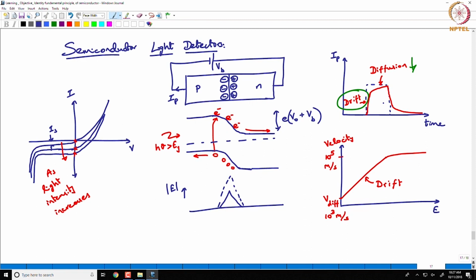So, those will contribute to the initial photocurrent, and then you have the slower charges coming out of this photodiode, right. The ones going through diffusion would have a slower time constant, they will come later essentially, right. And what we have fixed with the PIN structure is that now you can get a response something like this.